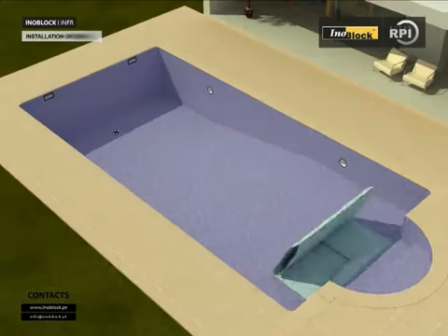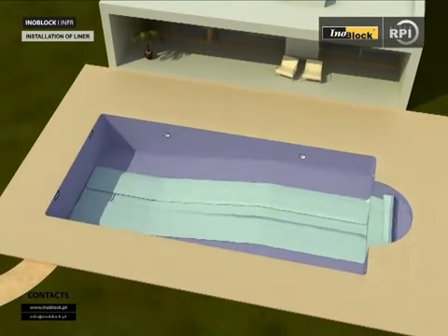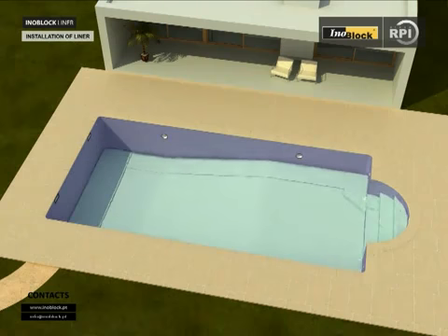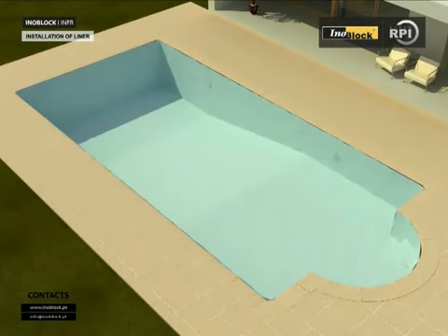Installation of liner. Cut out the underlay around the areas for the services: skimmers, drain, vacuum, lights and returns, and apply the gaskets supplied with each item. Then fix in place each of them using fixings supplied. The liner is factory supplied and made to fit the pool exactly. Start by placing the liner into the groove which runs around the top edge of the pool.